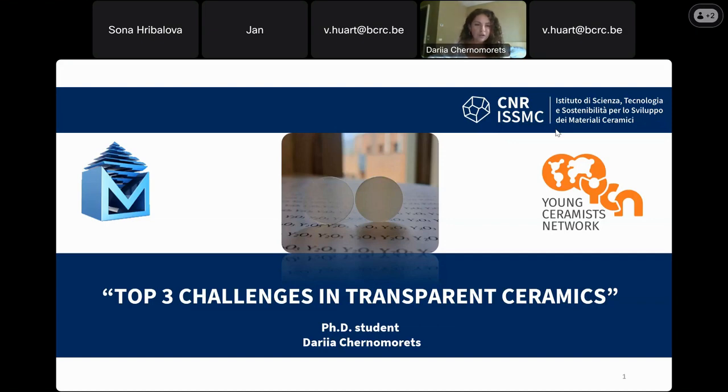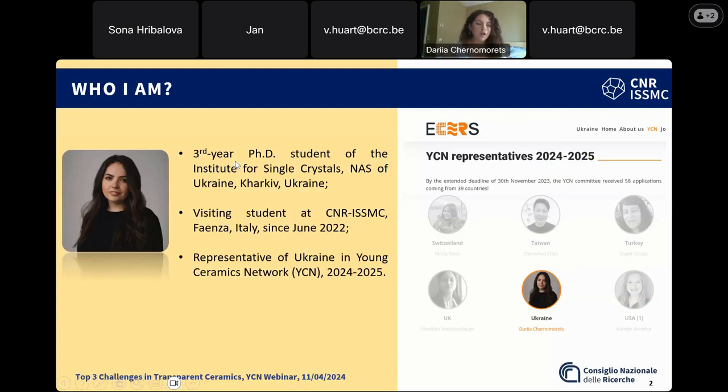But even the not polished sample exhibits quite good transparency. Now we move to direct ink writing, and the requirements are more or less the same, but in contrast to slip casting, we should have high viscosity and pseudoplastic behavior.